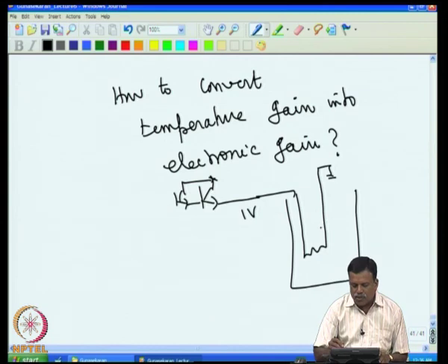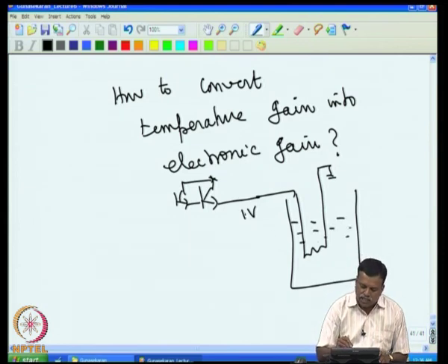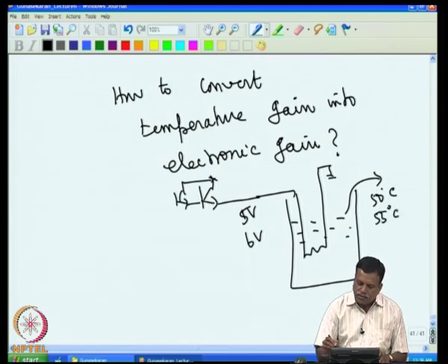Now, for example, 1 volt change may raise the temperature; assume in this case the temperature goes up and stabilizes. For example, originally it is say 5 volt, then temperature at this point was say 50 degree, then I give 6 volt, then temperature will go a little higher than this and stabilize, assume that it is 55 degree. That means, for every 1 volt, at 55 degree it stabilized, because at 55 degree the heat coming in is equal to heat going out.